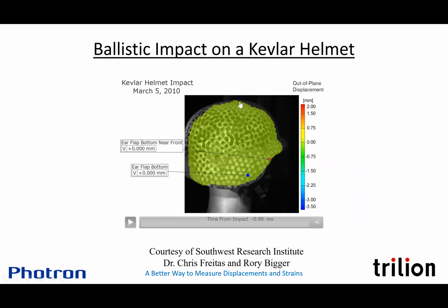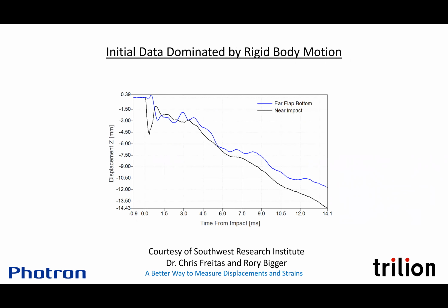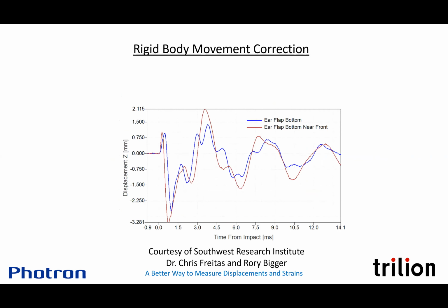If I only pick a narrow swath of points, I'm not going to be sensitive enough to tilting in this direction. And then the way we can assess it is, was that DC bias removed? Here we see the DC bias. Here we can see I did a good removal because I really am oscillating about 0.